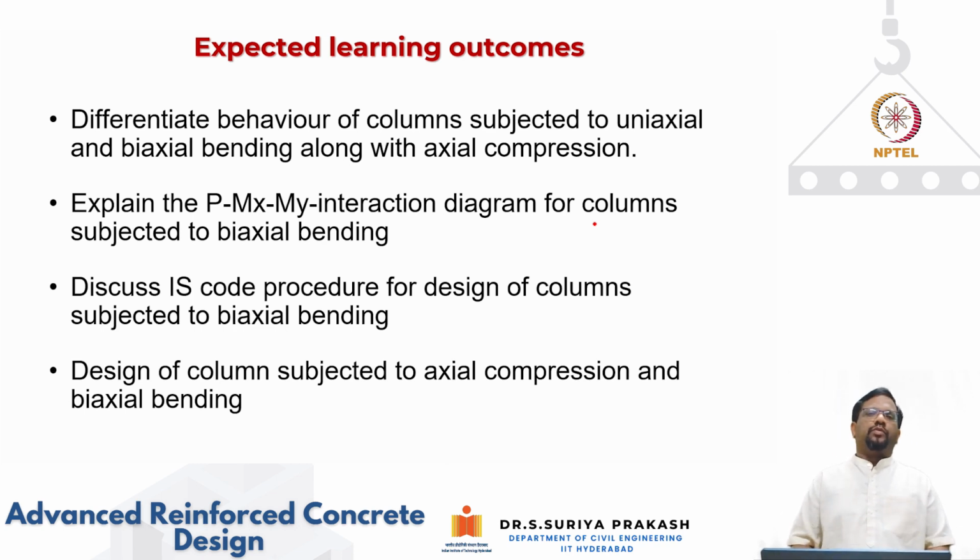After watching this video, the student should be able to differentiate the behavior of columns that are subjected to uniaxial and biaxial bending along with compression. What is the difference between uniaxial and biaxial bending? And they should be able to explain how the interaction diagram or surface, the P-Mx-My interaction diagram, looks for columns subjected to biaxial bending. In fact, this is a three-dimensional surface, and we will talk about how to derive that.